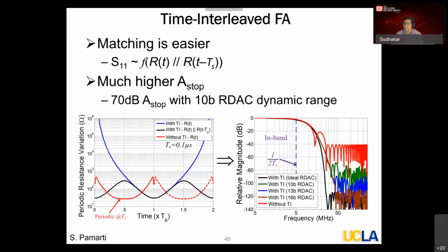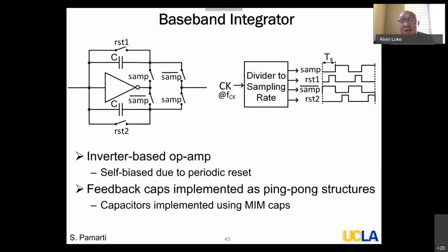Thank you. Just a comment to add. 10 bits makes the resistor DAC potentially quite large, even though you may have stronger switches and all that. Resistors are one of those things that are not really scaling from node to node into the advanced CMOS nodes, and it'll get prohibitively expensive. But yeah, it's very interesting work.